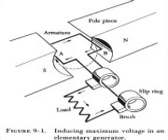Armature windings of a generator are spaced in such a way that, during rotation of the armature, there are certain positions when the brushes contact two adjacent segments, thereby shorting the armature windings to these segments. Usually, when the magnetic field is not distorted, there is no voltage being induced in the shorted windings, and, therefore, no harmful results occur from the shorting of the windings.